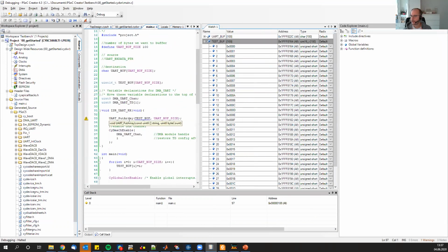How to transmit that from PSoC to MATLAB? You can, for example, just use this put array. The only thing you would have to be a little bit careful about here is that if I want to transmit this array, this data, then I cannot use only 100, because this would simply transmit only half of the array.